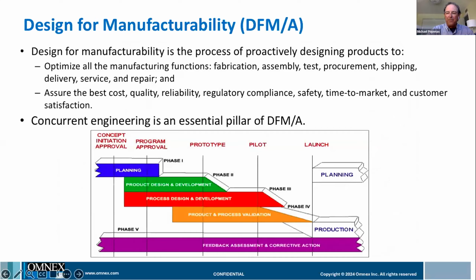So what we're talking about, first things is this idea of design for manufacturability. Can we make the part? Can we make it? I like to talk when I put this class on and I actually go into engagements to work on products. So, part of what we do at Omnex, of course, is training, but in hands-on work, especially when it comes to this type of engineering work, design for manufacturing and assembly. The first question I always tell these folks are you making products that your manufacturing system can make? Because if you're designing products that you can't make, you don't have a design.